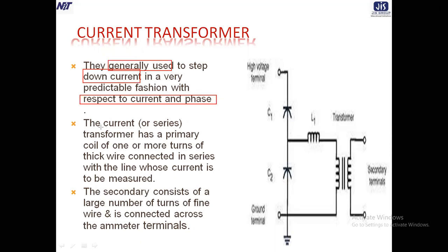So you have to remember this one. And about the current transformer, I can tell you that the secondary consists of a large number of turns of fine wire and is connected across the ammeter terminals.